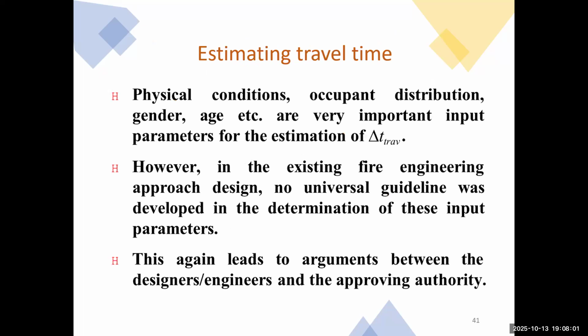And similarly, estimating travel time depends on physical conditions, such as occupant distribution, occupant density, age, mobility, and gender. So there is no universal guidance for selecting these input parameters, which again can lead to some debate. This is another reason why we need performance-based design.